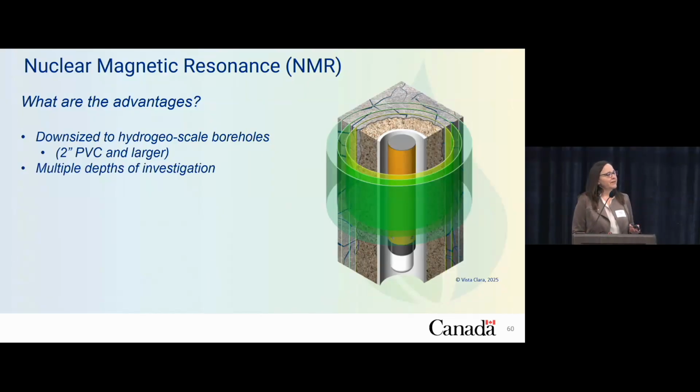This tool, as it's shown here, some of the models of this tool also have multiple diameters of investigation, and this is particularly useful if you're logging sediment boreholes because you can look beyond the disturbed zone, the completion, the sandpack, or the grout that's in the borehole. And finally, I think really important to all of us is that these tools measure porosity without requiring radioactive sources. So it's a little bit safer from a hydrogeological perspective. We're not having to integrate density or neutron tools, but we can still achieve a similar level of detail.